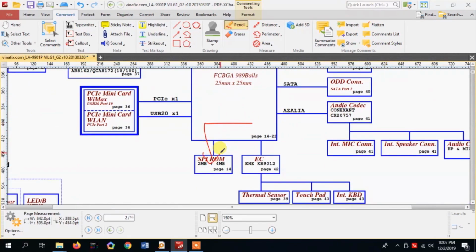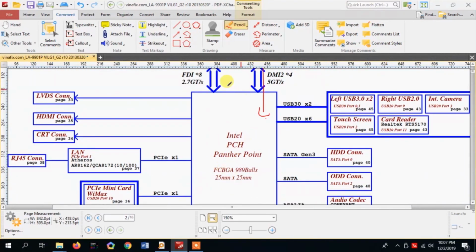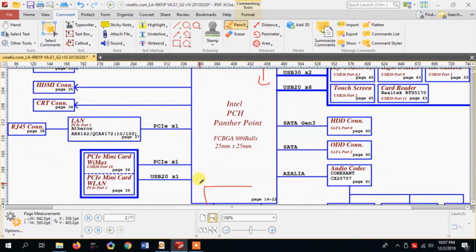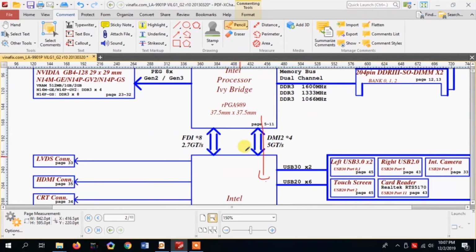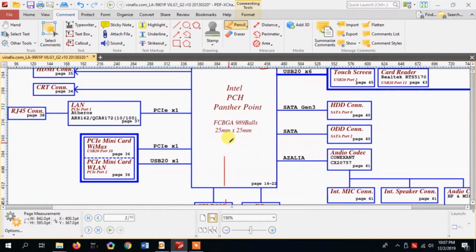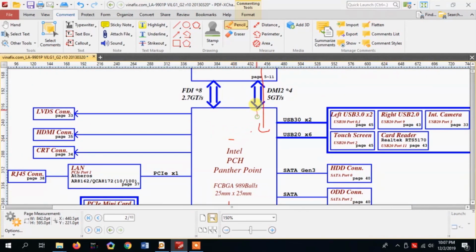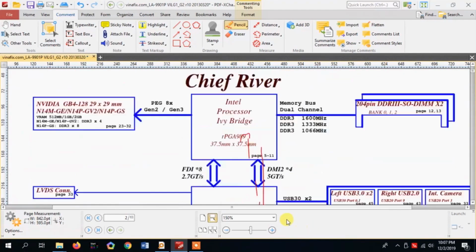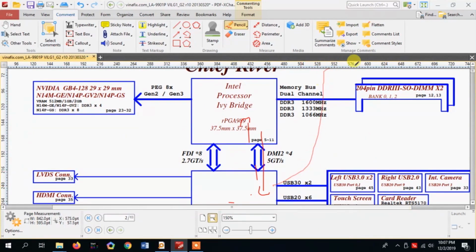After checking all supplies and working conditions, if the PCH working condition is in order, it reads its BIOS through the SPI bus. Once the BIOS is okay and intact, it sends an instruction back through the DMI bus to the CPU that the BIOS is okay. Then the CPU starts to run the code, and it will come into RAM.